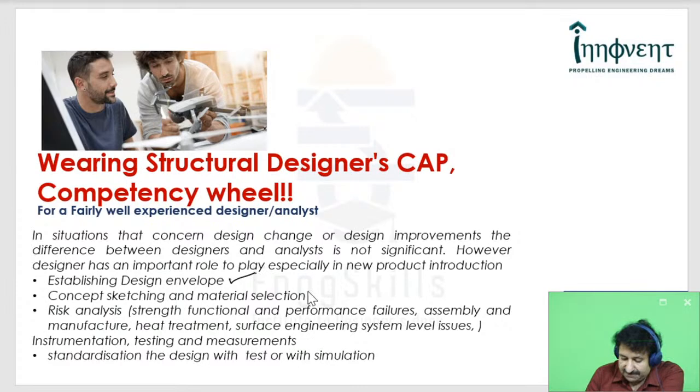And once you have the design space established, it is followed by concept sketching, and the concept must be evaluated for various risks. It need not just be strength failures. It can be a buildability issue, it can be a manufacturing issue, it can be a performance issue. So there can be several issues that have to be looked at before you select the best concept.